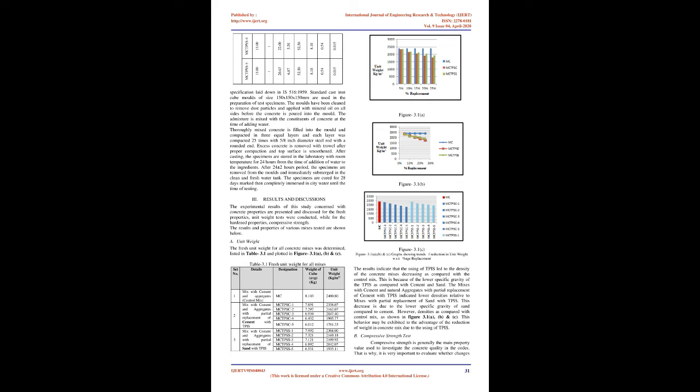C. Preparation, procedure of mixing and curing. The proportioning of quantity of both cement and aggregate is done by weight as per the concrete mix design. The water and the admixture are measured by volume. All measuring equipment were maintained in clean serviceable condition with their accuracy periodically checked. The workability tests are carried out immediately after mixing of concrete using the slump cone test.